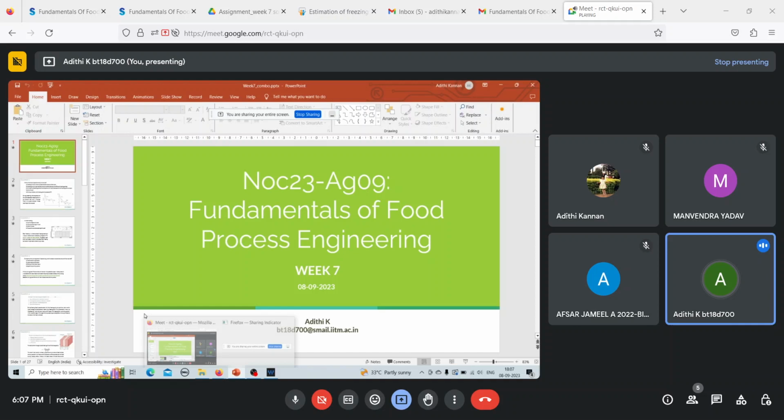And D, during nucleation, the freezing point increases to 0. That is at this stage. At S is where you have supercooled fluid, and once there is a nucleation that is happening, you will have the latent heat being removed, and because of that latent heat being removed during the nucleation stage, your temperature will slightly increase to the freezing point. That is to point B. So statement 4 is also correct.